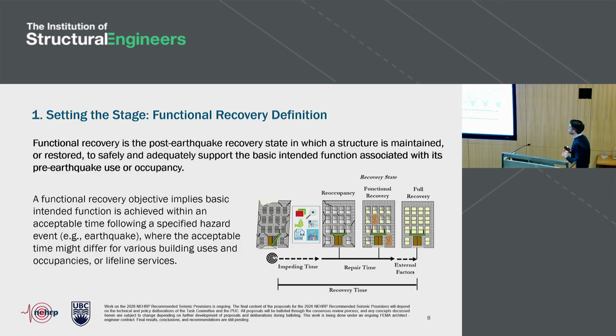And I think it's pretty important to emphasize that a functional recovery objective doesn't necessarily mean everything needs to be back up and running immediately after the earthquake. It recognizes there are different types of buildings that offer services that might be needed at different times, right? So there's a time component to this. It doesn't necessarily mean everything must work on day zero, right? Because that would be very costly, and we would be designing all of our buildings to maybe criteria that's unnecessary and maybe too conservative.